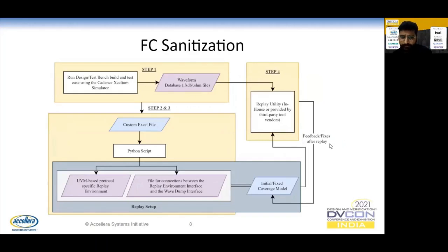A similar mechanism is used in the coverage sanity setup, where the waveform database is played over the coverage grid and coverage monitor. Instead of replaying it on an auto-generated test bench, here we replay the waveform on the existing coverage model and coverage monitors to see if the fixes are working or not.